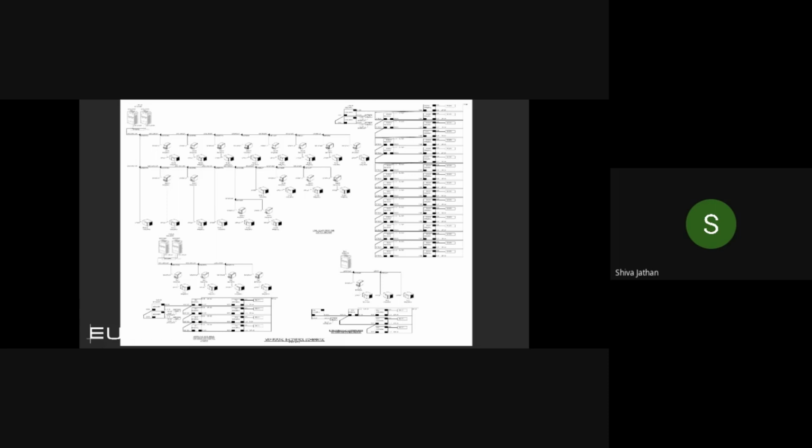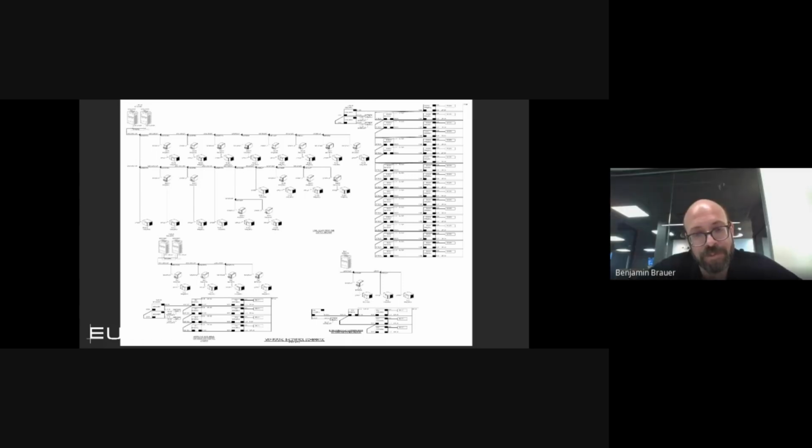Okay. Can I say that the first one, the VAV system, is kind of obsolete nowadays? VAV is somewhat obsolete. You don't see those in new buildings. I'm going to say you'll never find those designed for a new building, but we'll still be doing lots of TIs in buildings that have those systems in them. Especially with today's cost of steel, it requires a lot of sheet metal, a lot of ductwork, and the cost of sheet metal is just astronomical right now. So we will probably never see a new building with a VAV primary system ever again here in Vancouver. Okay. Thank you.